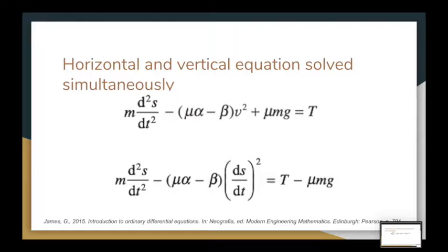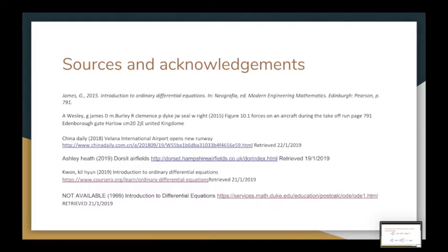Assuming thrust is constant, we are left with our final differential equation with respect to the first and second derivatives of time of the distance travelled by the aircraft. Being a differential equation expressed as the distance s travelled along a runway, us as engineers can now use this model to calculate the distance for the aircraft's lift to equal its weight as it hits flight speed.